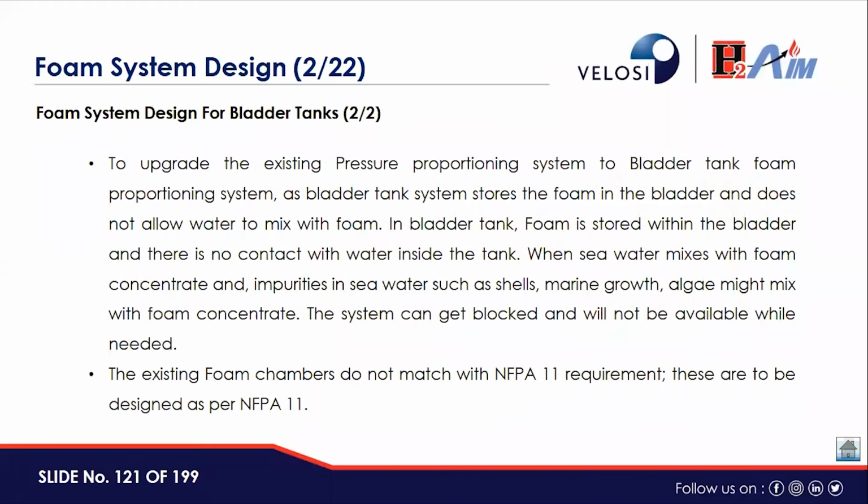Then we have to upgrade the existing pressure proportioning system to a bladder tank foam proportioning system, as the bladder tank system stores the foam in the bladder and does not allow water to mix with foam. In a bladder tank, foam is stored within the bladder and there is no contact with water inside the tank. When seawater mixes with the foam concentrate, impurities in seawater such as shells, marine growth, and algae might mix with the foam concentrate. The system can get blocked and will not be available when needed.